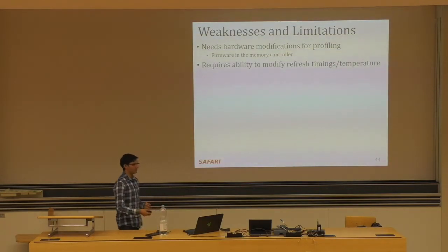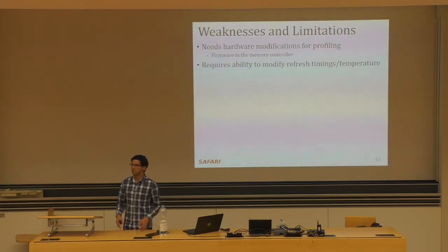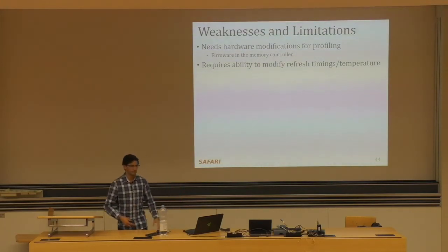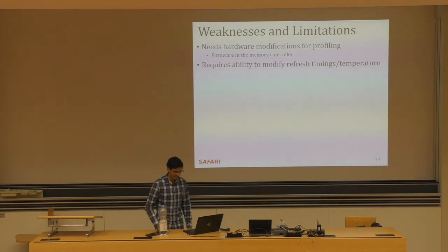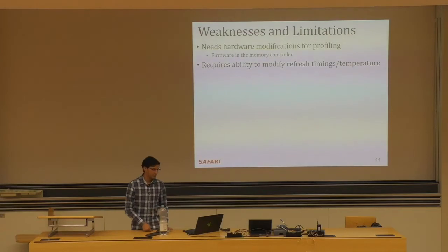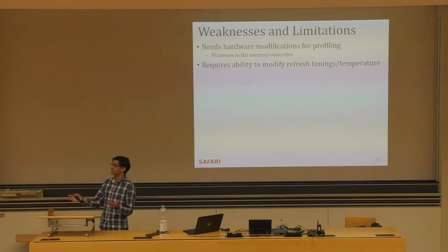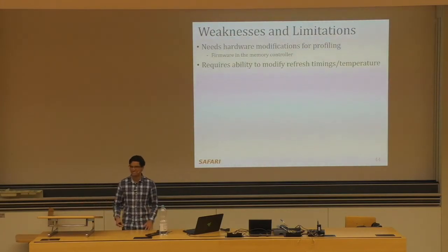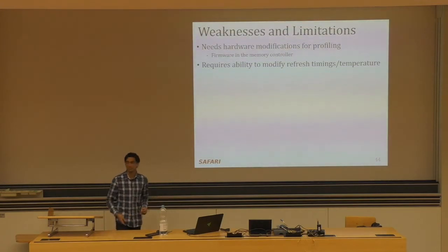Another weakness is that REAPER requires the ability to modify refresh timings and temperature in the first place. Right? So as I just said, not all CPUs will allow you to change the refresh interval. And if you can't change that, then you essentially can't apply this profiling methodology. Similarly with temperature. So let's say I'm trying to profile my laptop here. Short of having like a hairdryer and a fan blowing on it, there's no real way I can manipulate the temperature at will. And so then I can be passive about it and try and profile based on what the passive temperature changes are, or I can try and run some really intense code and heat up my machine or something like this. Yeah, so this is another limitation of the work.